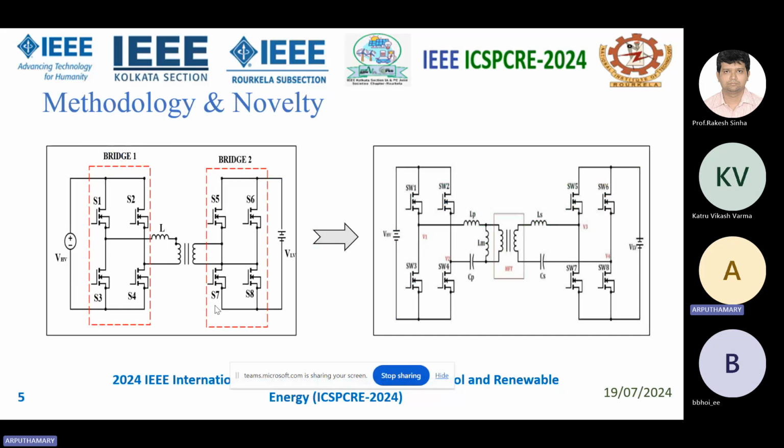But in future, for bidirectional power transportation, as my friends designed also, you need this kind of MOS switches. For that, we have to upgrade the switch as well as the number count. Previously, for 20 kilohertz switching frequency, we'll be using the IGBT. For more than 20 kilohertz, automatically we will have MOS switches.